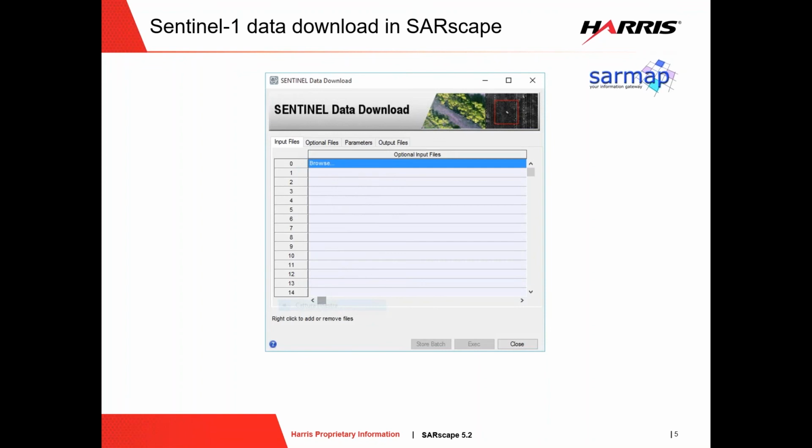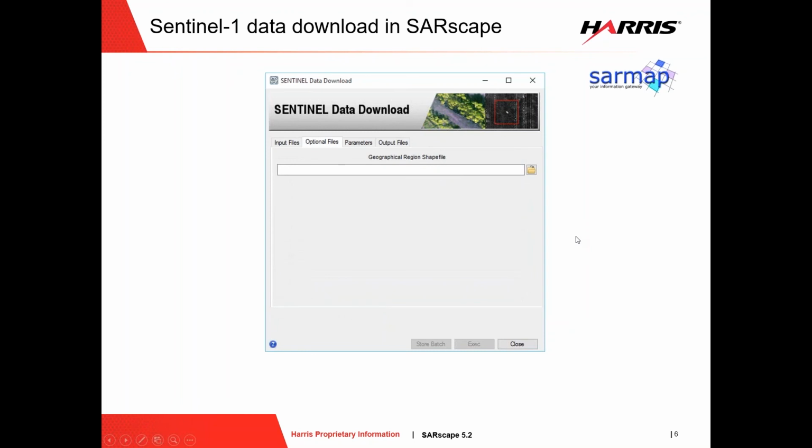So basically you can select Sentinel data from within ENVI in your area of interest. Or even if you have some reference files, some files you already downloaded, you can provide a list of files and ask this tool: please select in the InSAR archive all the Sentinel data that cover the same area, with the characteristics I'm going to tell you. You can specify reference SAR files, but you can also specify your region of interest through a shape file you can enter in this dialog.